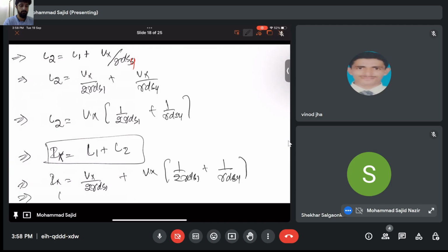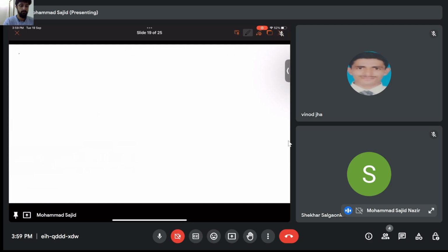So Ix is, you see, this is 1 by 2, 1 by 2. 2 times 1 by 2, that is 1. So this will be Vx times 1 by RDS1 plus 1 by RDS4. So Ix is Vx times 1 by RDS1 plus 1 by RDS4.